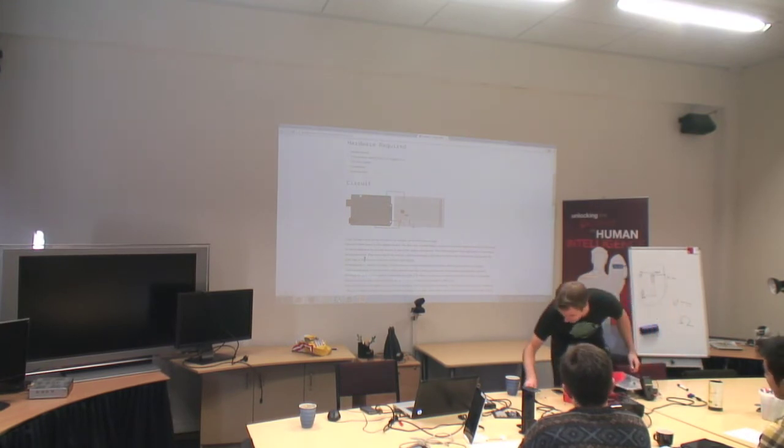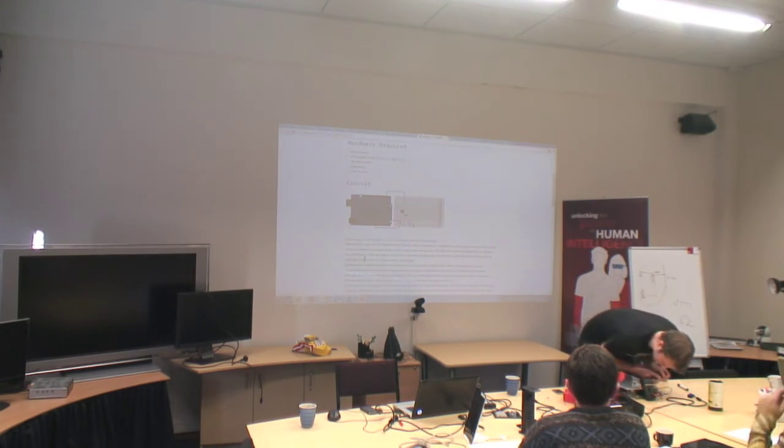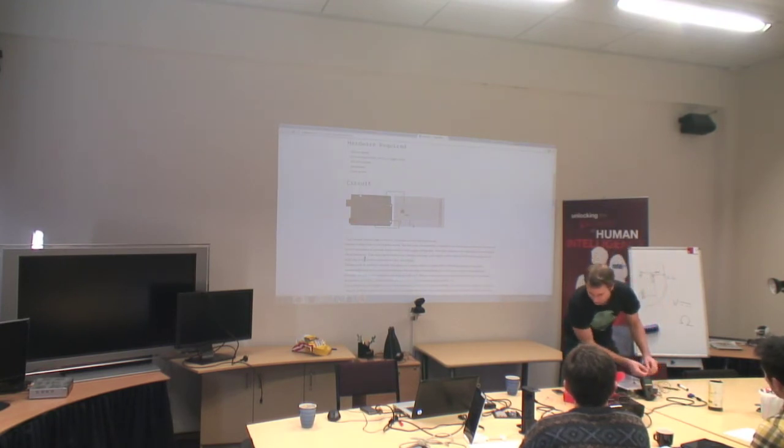If we then run through this resistor here, we'll see that that reads 322 ohms, and this is supposed to be a 330 ohm resistor, so it's close enough, it's within tolerance anyway.